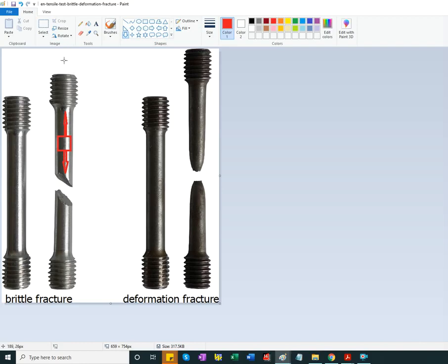Sigma is the tensile force, which is the axial force, divided by the cross-section area, and that is going to give us the principal stress, sigma x, if x is the longitudinal axis. Sigma y is going to be 0. And now the maximum shear element is going to be at 45 degrees. So it looks like for this material, failure occurred when we reached the maximum shear strength.